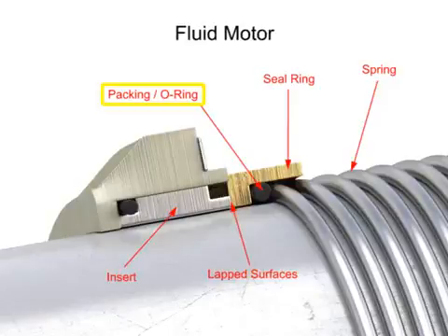Internal hydraulic pressure ensures the two surfaces are held in tight contact, but even this method is not leak-tight, and weepage is a common occurrence. Additionally, the lapped surfaces are sensitive to contaminants in the oil, which are abrasive and cause leakage to increase.